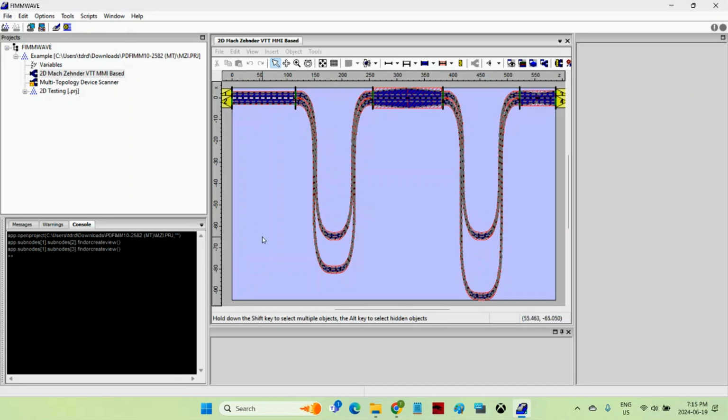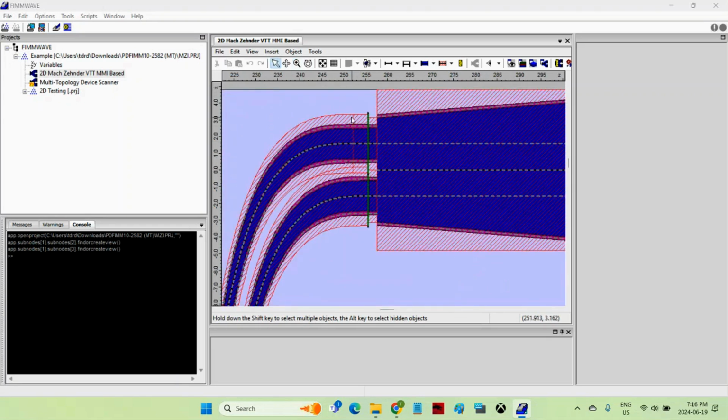So what we have in front of us here is a series of waveguides that have been connected together, and on top of all of the waveguide areas are these computational regions, which have been defined by the user setting up this model. It's in these computational regions that the EME method will solve the modes and propagate the modes through the waveguides and calculate the coupling between the regions.